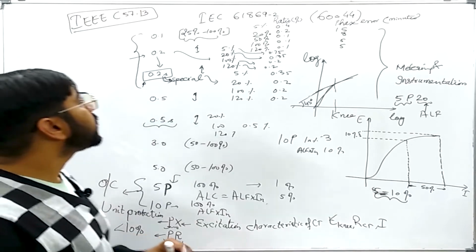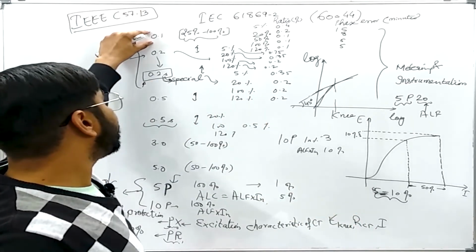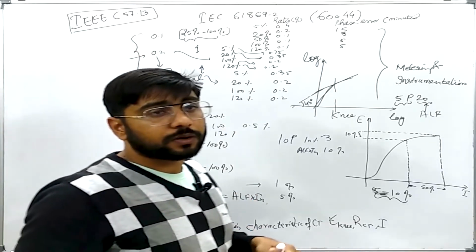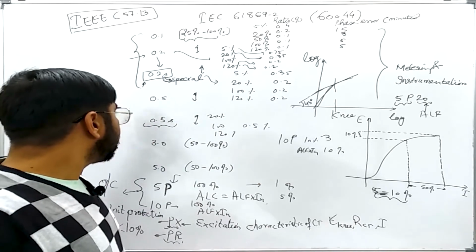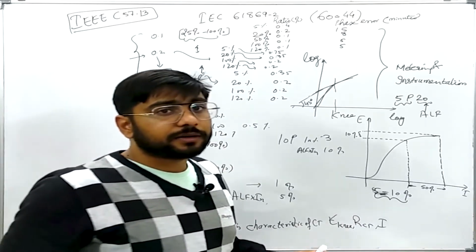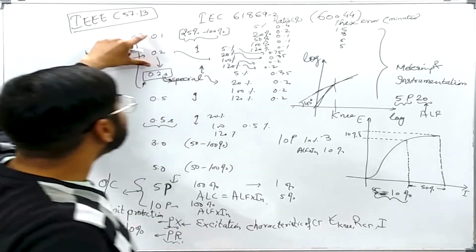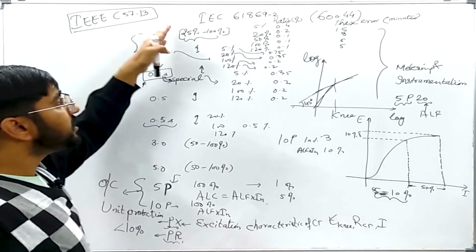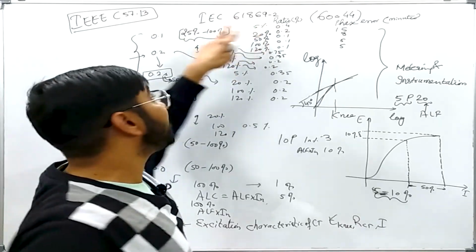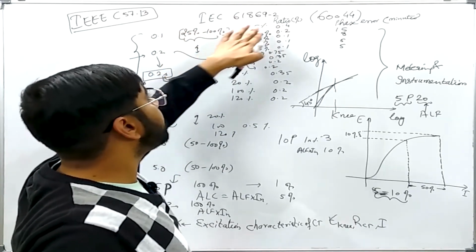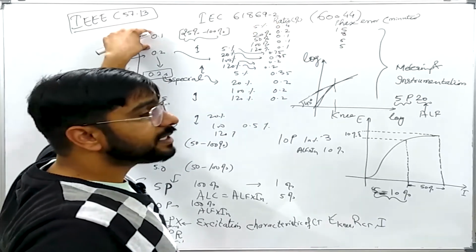Okay, then similarly in IEEE also we have metering classes 0.1, 0.3 like that. 0.2S is also a special class, but in the protection part the nomenclature is a little different in the IEEE. Similarly, this 0.1, 0.3 has different criteria in IEEE. So we should refer to IEEE to find the various ratio and phase errors for the metering CTs.